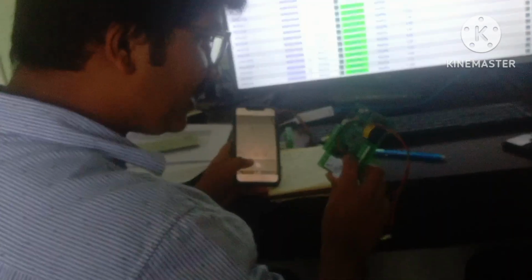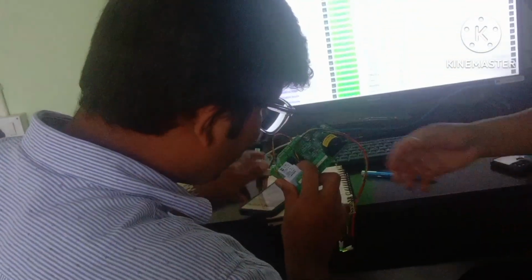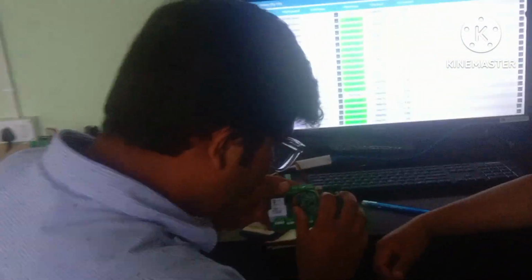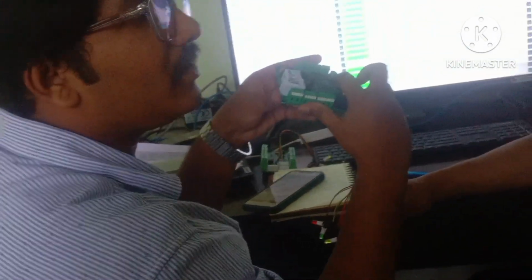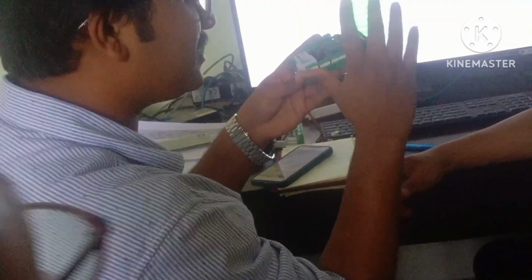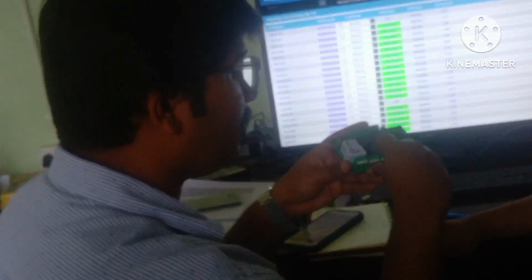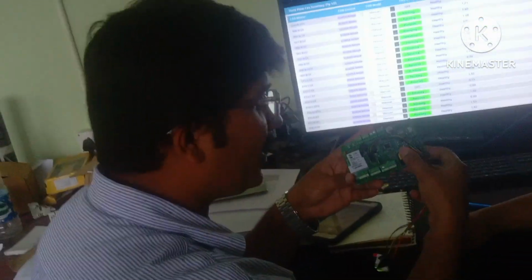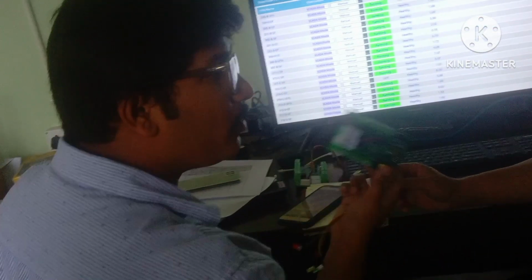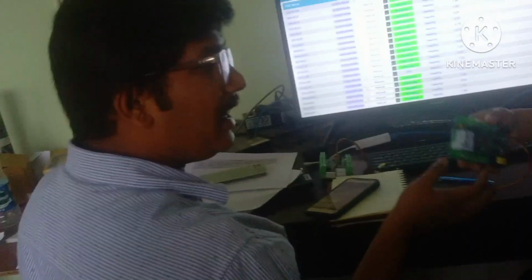And you see that this card is not working. Here are basically LED indications. If you see here, D5 is written here. This is a small LED which indicates that this card is on. And here is also one LED, D4. So if you open and you find that the light is not blinking, not coming, that means the card has stopped working, due to power fluctuation or anything.